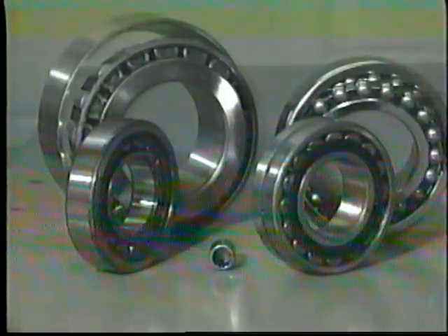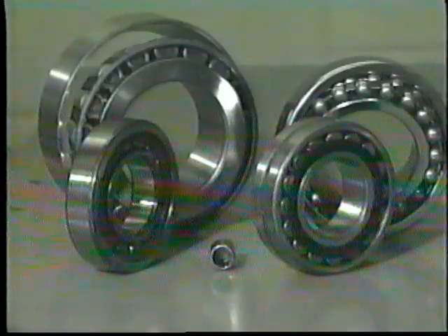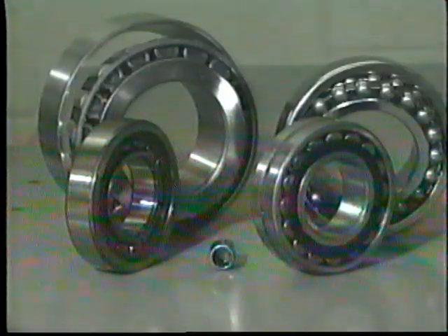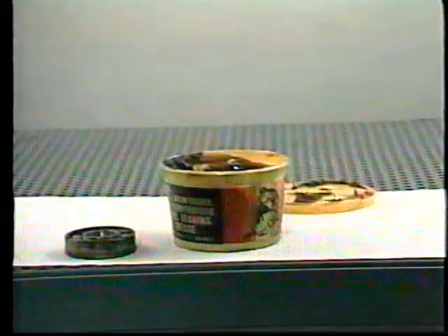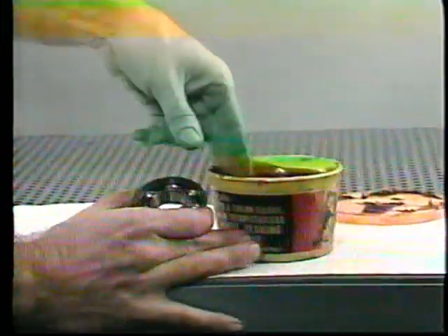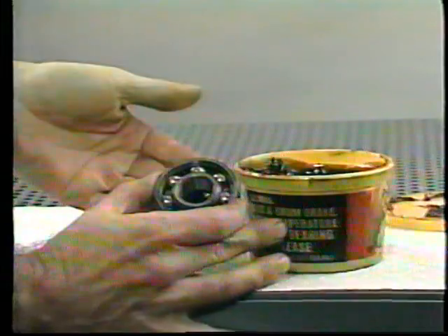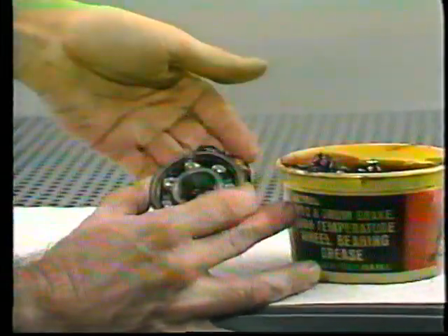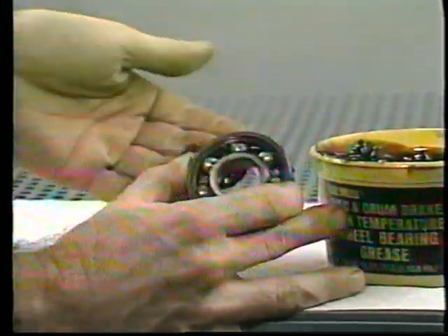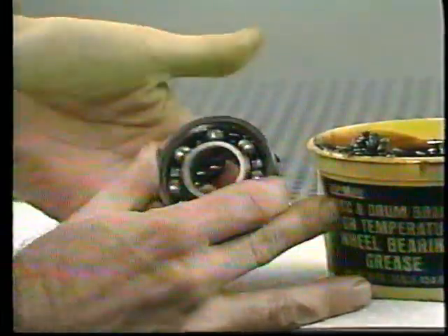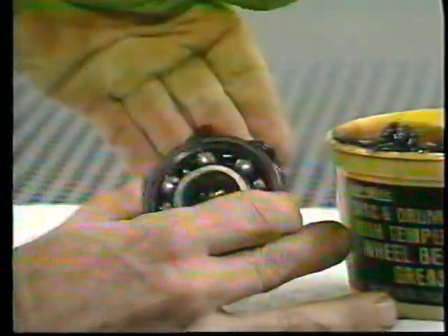Rolling element bearings may also require lubrication at the time of installation. When this is done, it must be done correctly. Cleanliness is essential. Hands, tools, clothes, and the work surface must be absolutely clean. New, fresh grease must be pushed completely through the bearing from one side to the other in order to coat all parts. This can be done by hand, but it is preferable to use a tool to pack the bearing.